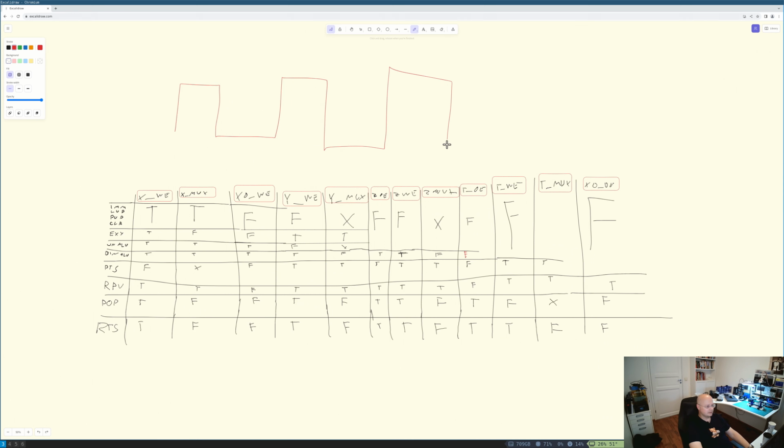And I was also asked why the clock signal is square. The reason for that, I almost explained: we need to wait for the sequential signals to stabilize. And for this, we need to have some pretty strong and easily detectable long period. Like a long period of low voltage, or a long period of high voltage, doesn't matter. And we would like to minimize the change time, like rise time or fall time, between those levels.